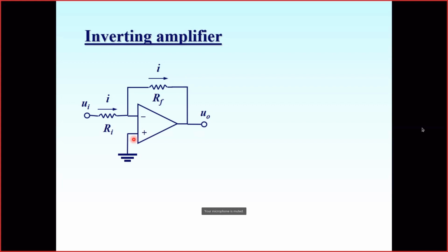There is some operation of this circuit. So the circuit operates like this. If for some moment the voltage, for instance, on the inverting input starts to grow, it immediately causes an increment in the output voltage, and the voltage on the inverting input will increase too. If this grows, this grows. If this falls down, this will fall down. So the amplifier itself, because of this feedback, will keep the inputs at the same voltage.